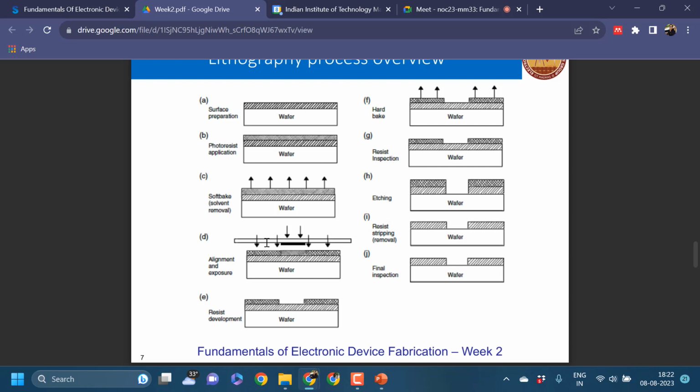Positive photoresist allows the light to pass through it and it is soluble to the light. Yeah. And negative photoresist is insoluble to the light. Yeah, so basically, positive means that exposure to light makes it soluble. Negative means that exposure makes it insoluble. So once it becomes soluble, when we are using an etchant or an evaporating substance, when it is removed, it becomes more soluble in case of positive. In negative, it's the reverse, meaning that exposure makes it insoluble. So that is the case with positive and negative photoresist.